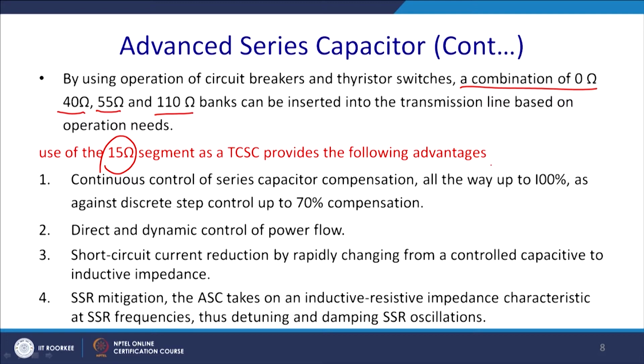Continuous control of the series capacitor compensation all the way up to 100%, and second, the discrete step control of about 70%. Direct and dynamic flow of power is also possible.